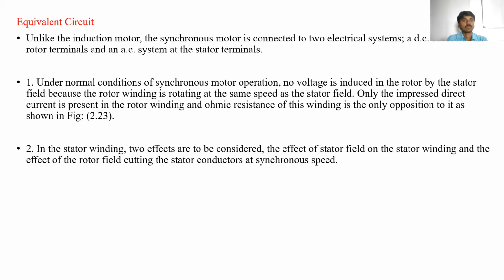So you can see here the equivalent circuit diagram. You have already studied the equivalent circuit of the synchronous motor in the electrical machines subject. Unlike the induction motor, the synchronous motor is connected to two electrical systems: a DC source to the rotor terminals and an AC system to the stator terminals.